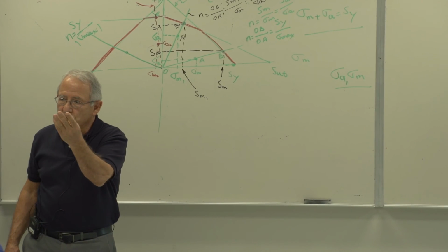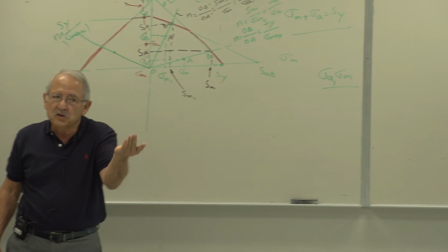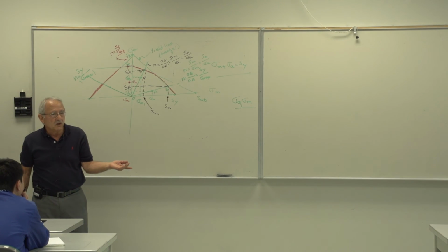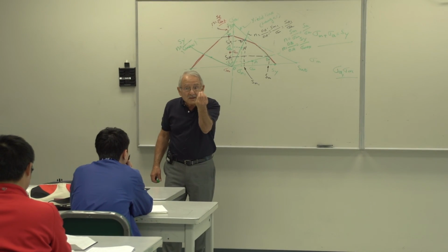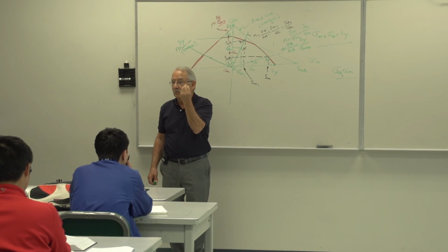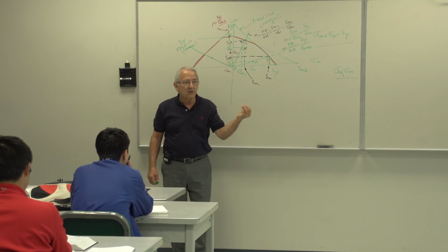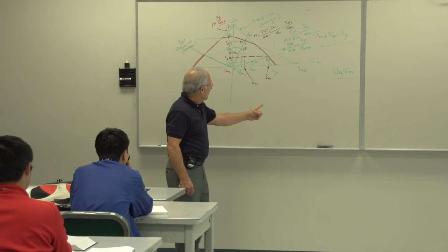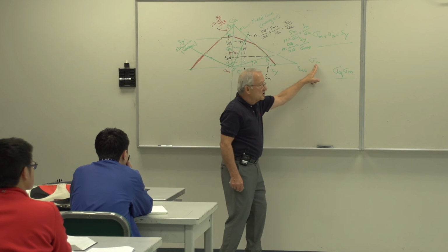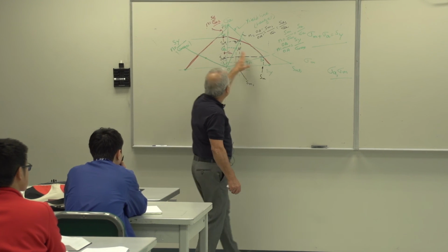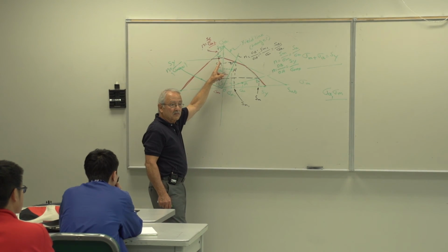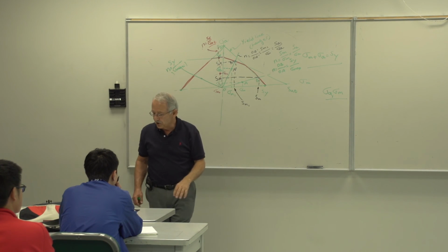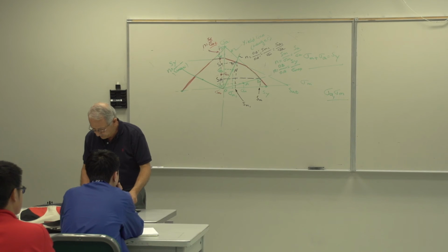So we take normal stresses, shear stresses, axial, maybe bending, whatever, and we combine them all into that sigma prime. We do exactly the same thing here, except we do it twice. We do it once for the mean stress, once for the alternating stress. Okay? The procedure is this. I will write it on the board.